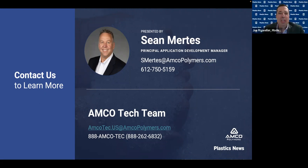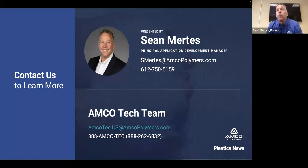How much do DMA curves change among specific grades within the same class of materials? That's a great question. Your polycarbonate typically is polycarbonate. You do get changes with... I actually have one that I was going to include in this. I wanted to get some more information for the seminar, just timing didn't work out, but I have a DMA showing a polypropylene with a nucleated polypropylene, just to say, hey, what kind of modulus difference do I get by having that extra